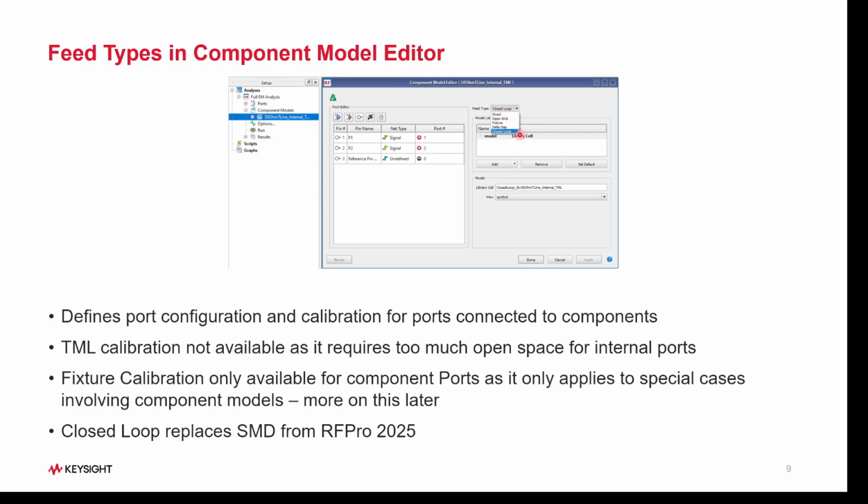Direct is there. TML is not available because it requires too much open space, as we'll see shortly. Fixture is only available for component ports, as it only applies to special cases involving component models. I'll spend a bit more time on this later. And closed loop replaces SMD from RF Pro 2025, as we just saw.